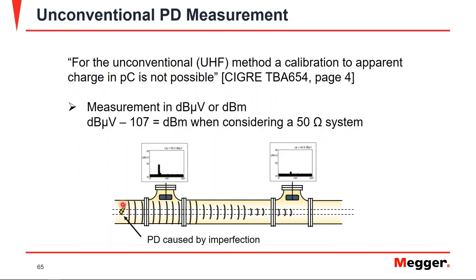And you can see that your partial discharge defect, again, sends out electromagnetic wave signals, and you can decouple them using the UHF sensors. You can see the effect of the attenuation and other high frequency signal effects as the signal starts to attenuate and lower due to dispersion and reflections and so on.